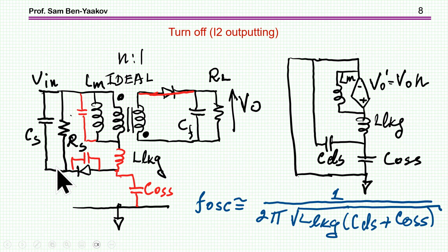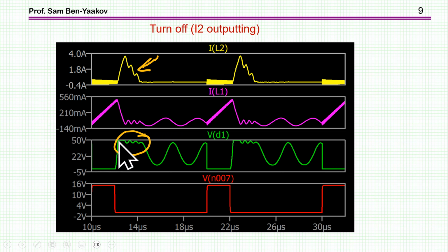The idea is to generate a voltage, plus here and minus here, such that it is clamping the voltage of the MOSFET, of the drain, to this value, just to protect it. We can see it here. This is the time that we have the clamp, and then the voltage of the drain is actually a bit lower, and then we have this oscillation.